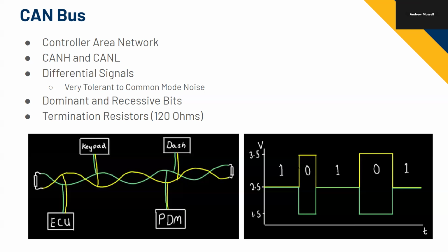So it goes in and asks, is it 120 ohms matched impedance? If I get to a part like this where there's a junction, I'll see less impedance, right? Because I can go two ways. I will basically send a second wave back that gets reflected because I hit a discontinuity in the harness. I'm not doing this full justice, but you can watch a bunch of stuff about transmission lines. It's very important for high-speed communication.